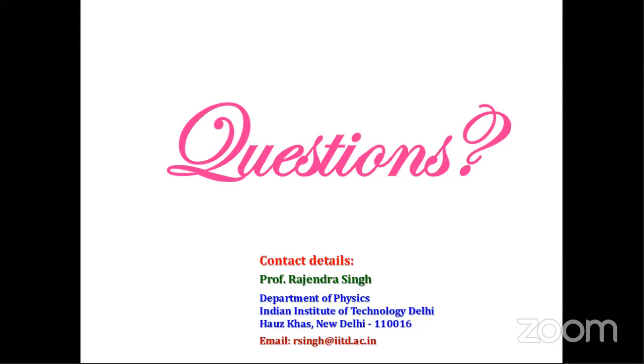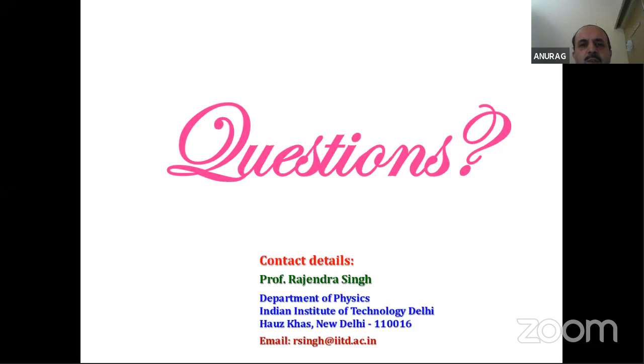Rajesh Kumar Sukla wants to know how to measure resistivity with a low cost or homemade apparatus, without using a Keithley apparatus. Yeah. So as I have told you, the van der Pauw method is the simplest in that sense. There is no restriction on what kind of geometry of the sample there should be, and what kind of geometry of the 4 contacts. So that is actually the best method for low cost electrical measurements.